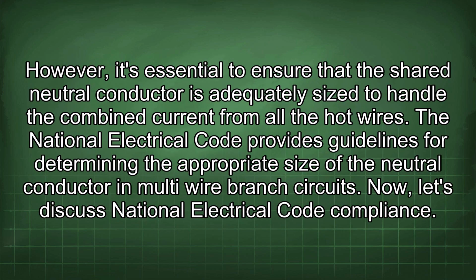However, it's essential to ensure that the shared neutral conductor is adequately sized to handle the combined current from all the hot wires. The National Electrical Code provides guidelines for determining the appropriate size of the neutral conductor in multi-wire branch circuits. Now let's discuss National Electrical Code compliance.